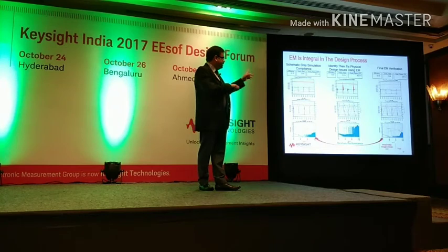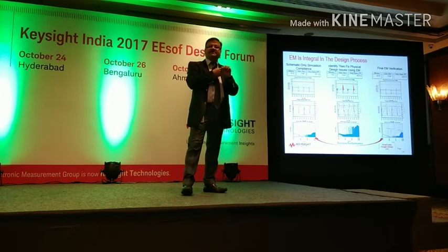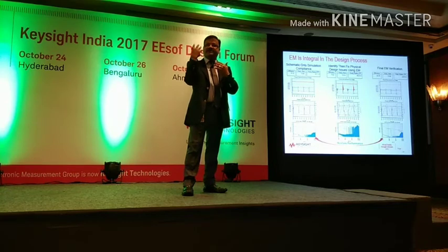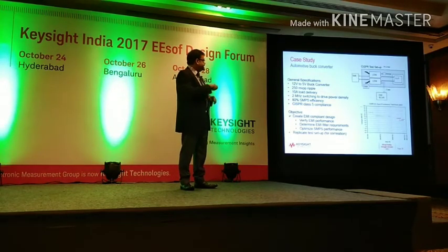Then we took it, understood the whole requirement, we fixed the layout and the EMI filter or whatever, and that's the final performance, which looks very, very similar to what you achieved in the schematic. You cannot achieve better than the schematic, that's your golden reference. So the idea is to make layout as transparent as you can so that you achieve back the same schematic performance. Right? So here's a design case study.